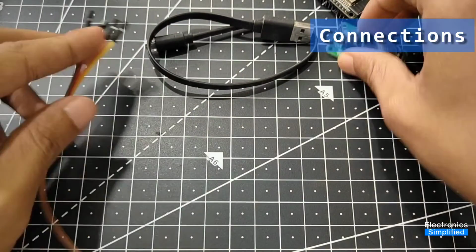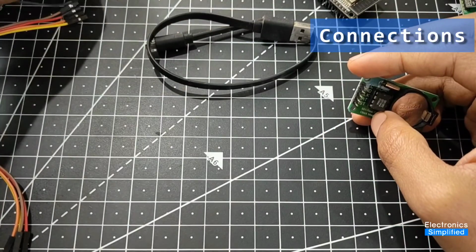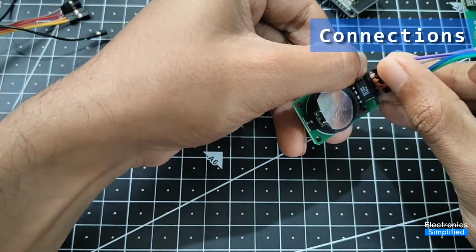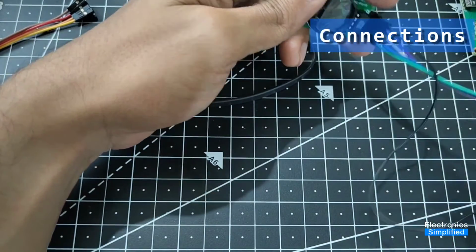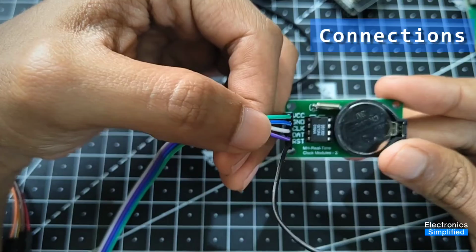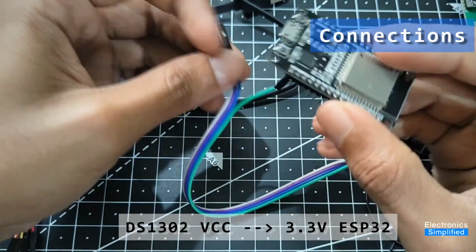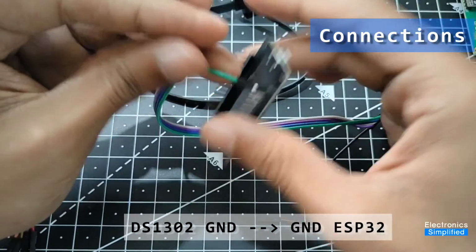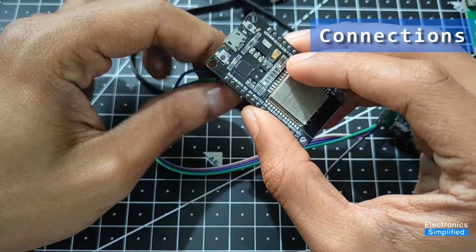I'm going to start connecting the real-time clock module. Right, so now I'm going to connect the VCC to the 3 volts of my ESP32, and then the ground pin, that is blue, goes to ground on my ESP32. So I'll quickly connect it,